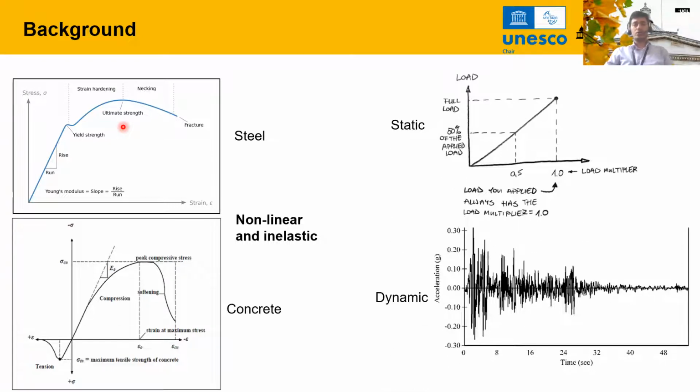Similarly, with respect to the loads, if we consider the seismic load, earthquake load is a static load, which increases monotonically in steps, for example, like this, which is the equivalent load or the static procedure that is codified in many of the codes historically. So that is the static process of load representation. But in reality, the earthquake loads are dynamic and cyclic, as you can see in this time history.